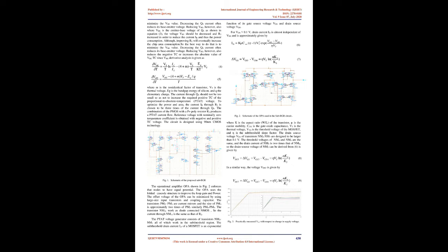CMOS VRs [8-12] have several remaining issues, such as leakage current consumption, low reference voltage of 257.5 mV, and wide area. In this work, we propose a CMOS sub-threshold voltage reference, VR, implemented in a circuit. The reference voltage is biased to be temperature independent, increasing the performance and accuracy of the circuit with very low sensitivity to variations in process and supply voltage. For the rest of the paper, Section 2 presents the materials and methods of the voltage reference. The measurement results of a prototype design in a standard 90nm CMOS process are introduced and analyzed in Section 3.